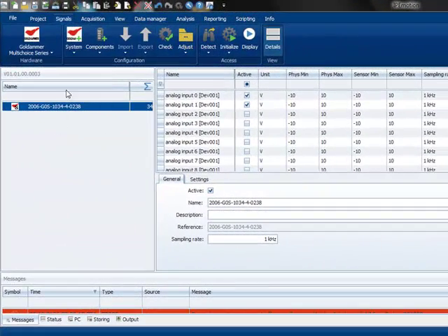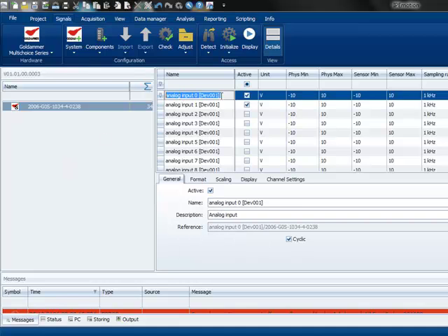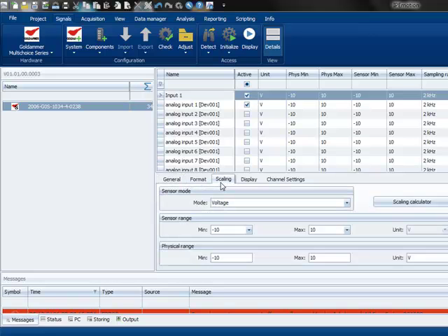Here on this tree you have a list of the units, and then you have your channel grid. Here in the channel grid you define your channel name. Yeah, this is my input, of course. You specify your sample rate. We can go here at 2 kilohertz, for instance, sample rate. And we have here, most important for analog inputs, the scaling interface. So here on this interface you convert your electrical signal voltage into engineering units.